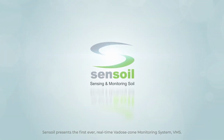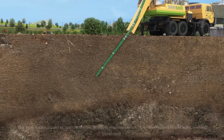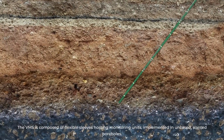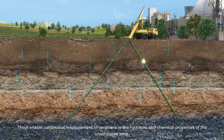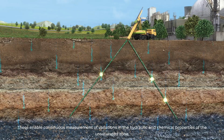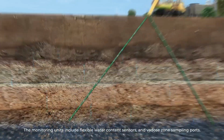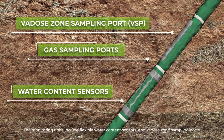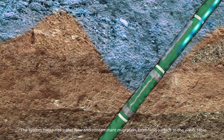Sensoil presents the first ever real-time Vadose Zone Monitoring System, VMS. The VMS is composed of flexible sleeves hosting monitoring units, implemented in uncased, slanted boreholes. These enable continuous measurements of variations in the hydraulic and chemical properties of the unsaturated zone. The monitoring units include flexible water content sensors and Vadose Zone sampling ports. The system measures water flow and contaminant migration from land surface to the water table.